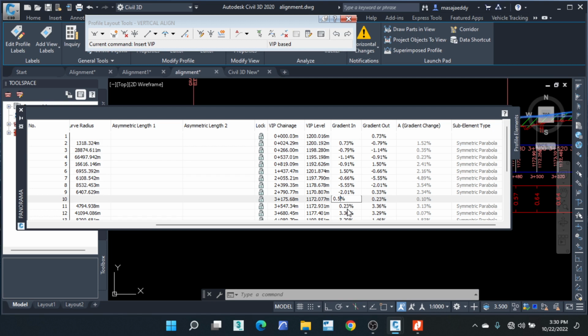For a 900 millimeter culvert, we are considering something like 800 millimeters above the culvert. That is excluding the pavement. It has to be up to the formation level. If it is less than that, then the culvert will have to be encased.